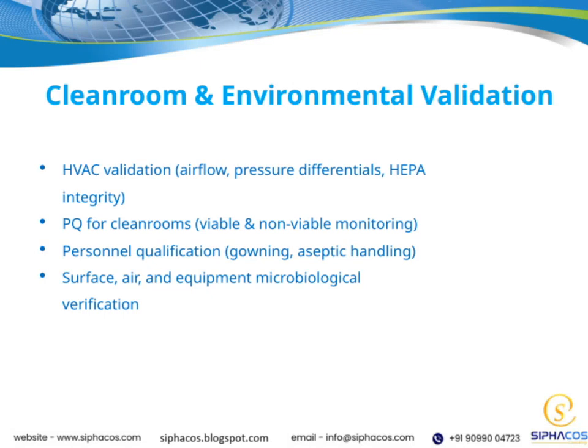Now, let's discuss some critical aspects of our cleanroom validation process. First, HVAC validation is essential. This involves verifying airflow patterns, pressure differentials, and ensuring the integrity of HEPA filters. These elements are the backbone of maintaining a controlled environment, preventing contamination, and ensuring product safety.